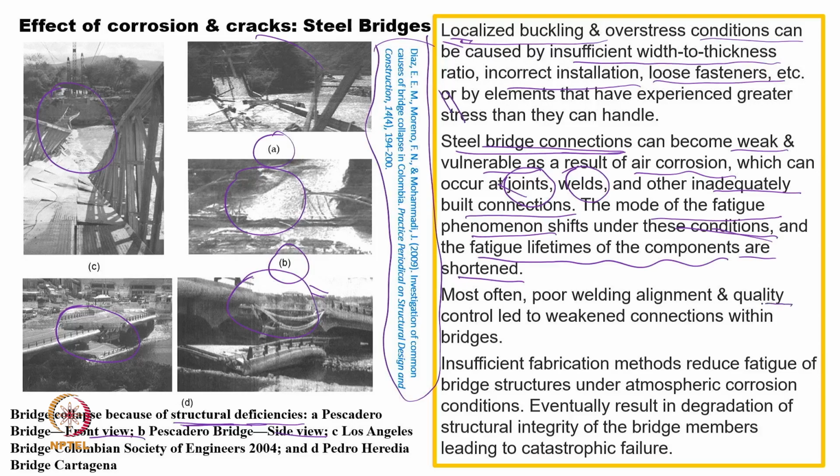And as far as my knowledge is concerned, in this case poor welding gives us sites for corrosion to set in, and that corrosion really weakens the unit completely. So, I can finally blame insufficient fabrication. Maybe the design is perfect, but fabrication is not correct, or fabrication methods are not correct. As I mentioned, the welding which has been done may not be correct. So, that will not be realized instantaneously, it will come after time. So, the performance is deteriorating with time.